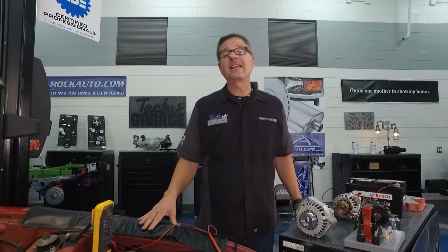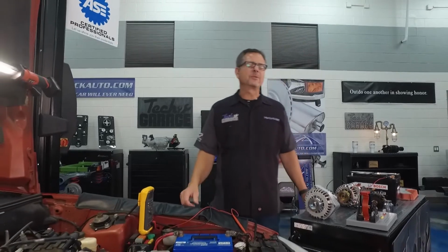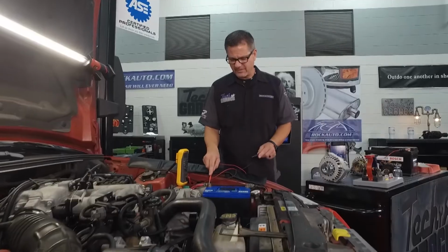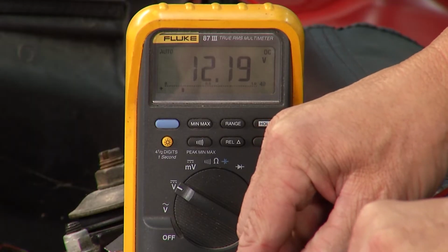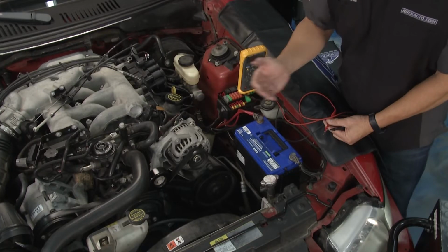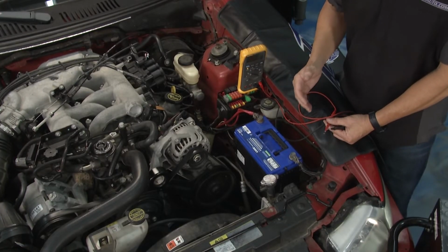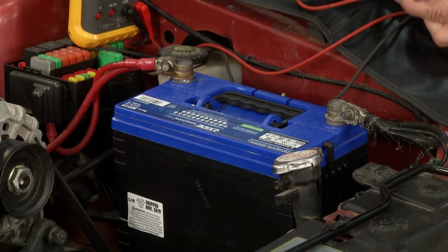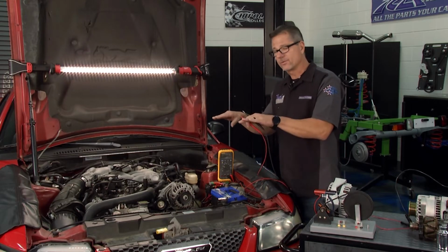But you know what? You guys came here for the tech tips. And here's a tech tip you can do right out in the driveway. It's called OCV, open circuit voltage. Just come across the battery, and it's sitting at about 12 volts. Now, when we start the car, we should actually raise the voltage. The voltage should go up because I need the alternator to produce more than the battery does. Kind of like if I put 12 pounds of pressure here and 12 pounds there, it wouldn't go anywhere.